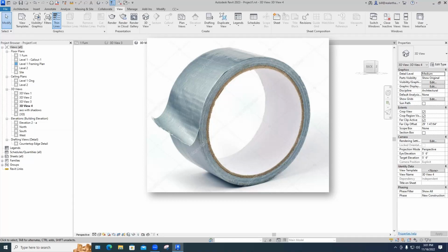Let's think. We could draw a circle with a circle inside it and extrude it, and we get that. Another would be what we just did with the planter, which is a shape and an axis of revolution and spin it, and then we get that same shape. We could create a solid cylinder and then a smaller void cylinder and subtract the void from the solid. Or we have a circle and a skinny rectangular shape, a sweep, and sweep that around that way. So that's 4 ways. That's all I can think of.